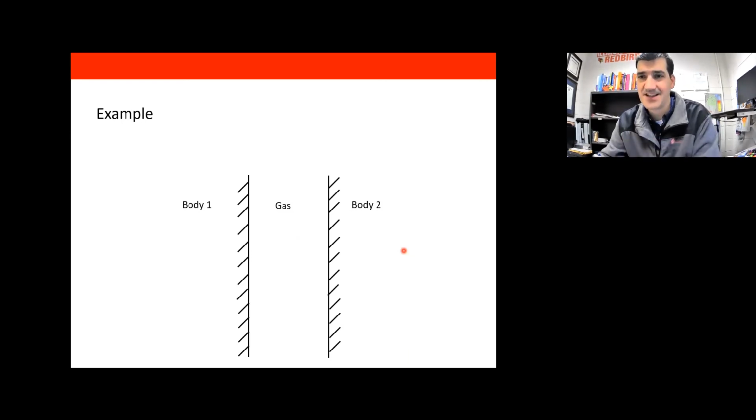All right, so I've said a lot about that. We're going to have some method of heat transfer between here and here. We're also going to have radiation, and I don't think I mentioned that yet. If there's a temperature difference between these two bodies, then we are going to have radiation heat transfer. The exact amount depends on these bodies, but in general, we're going to have radiation heat transfer between these two objects that are only separated by this layer of gas.